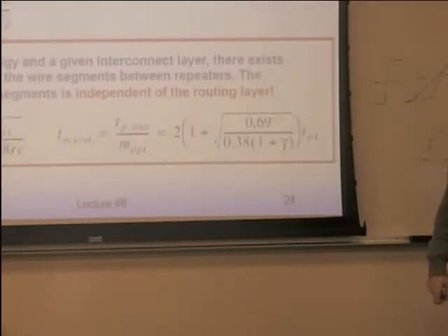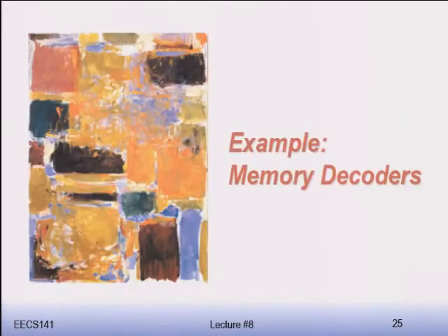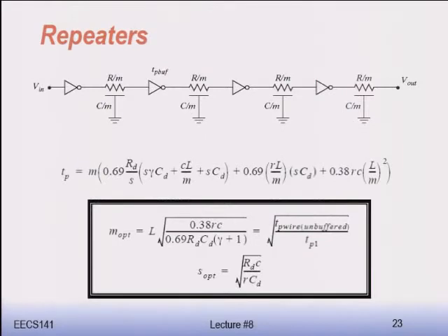So you can use an even more sophisticated model. Actually, okay, so I think then the interesting thing is what you get is that after you do this optimization, essentially you are balancing out the delay of the wire with the delay of the inverter, okay? So in other words, you are creating a wire that is about as good as the inverter.